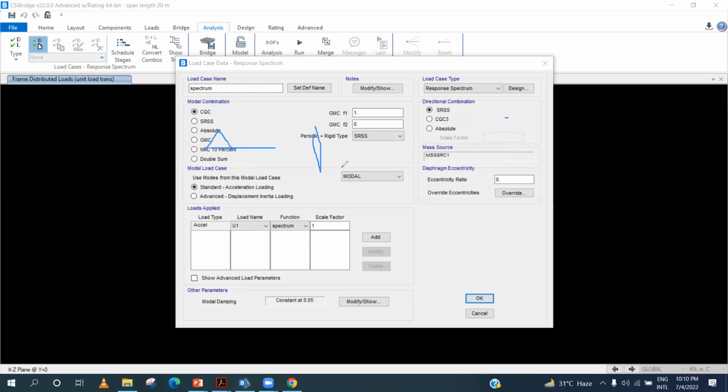So in that case, you will have to take the vertical effect. But mostly, in 99% of bridges we don't take the vertical effect, because we don't construct bridges near the fault zones, as it is not very desirable. Aziz, just to tell you one thing, in the building codes we have a vertical effect, even if it is in zone one or zone two.